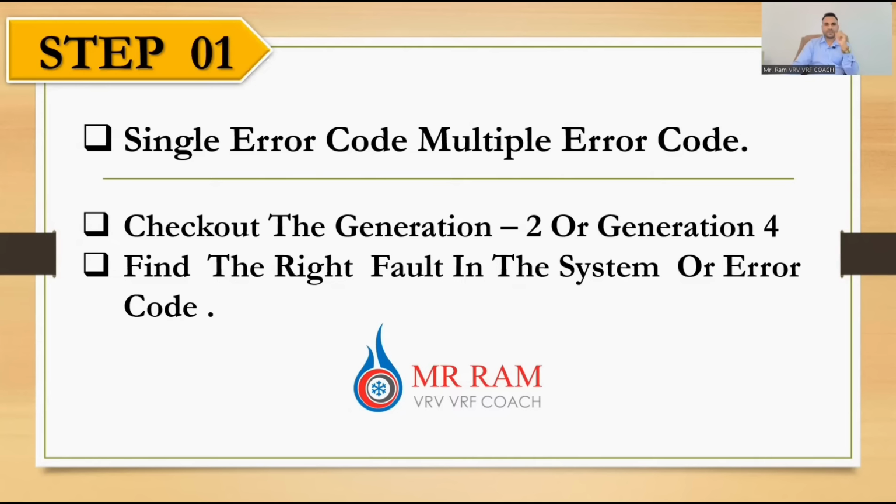So dear friends, when we go for troubleshooting the error code, we can find the error code on the thermostat, central control, and the outdoor unit's display board. Basically we have to know whether only a single error code is showing on all thermostats, or whether multiple indoor units have different error codes. Maybe sometimes a subcode is also blinking on the thermostat display. But especially in VRV and VRF systems, we get a similar error code on all indoor and outdoor units. So dear friends, we first have to find out whether it is a single error code or multiple error codes, because they have different resolving processes.